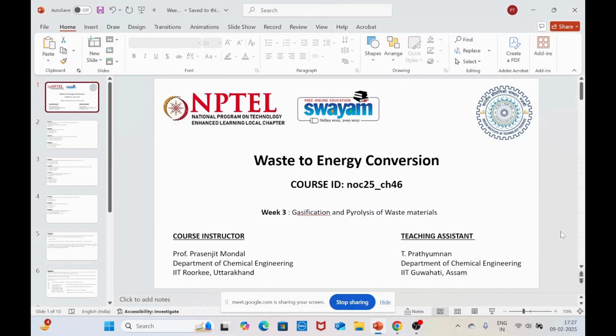All these three are fed from the top of the gasifier. So there is better flow and better contact between the biomass and the fuel. In entrained bed gasifiers, the combustion zone temperature is also quite high. It's not like fluidized bed. Here we maintain around 1400 or 1500 degrees Celsius.